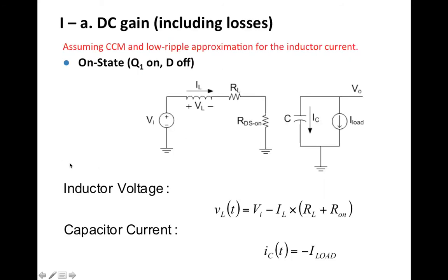Now our goal is to recalculate this DC gain relationship between the output voltage and input voltage when we have lossy components. Specifically, we add a series resistance to the inductor, and also we assume some R_DS(on) or conduction resistance for the MOSFET device when it turns on. Also, we assume that our diode is non-ideal, meaning that there is a forward voltage whenever it conducts.